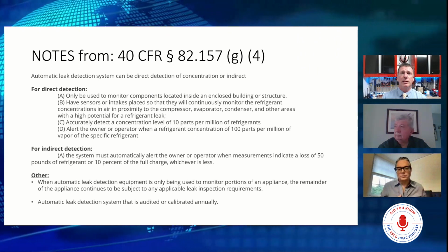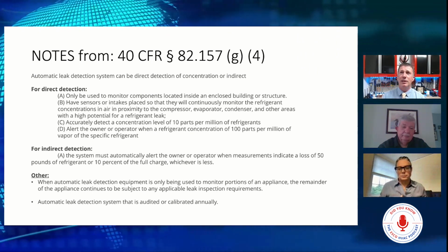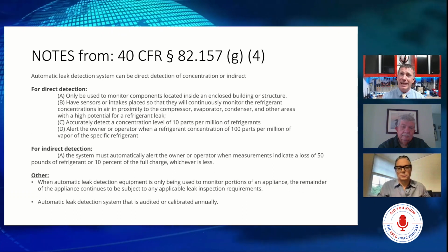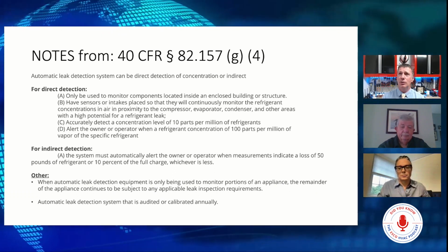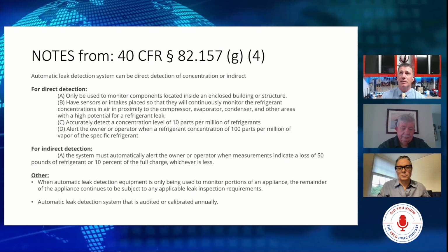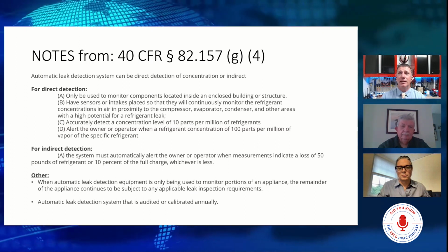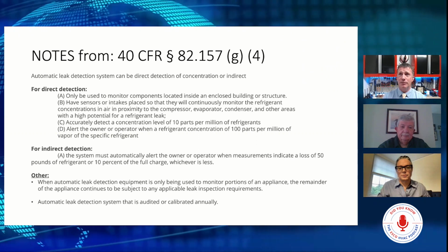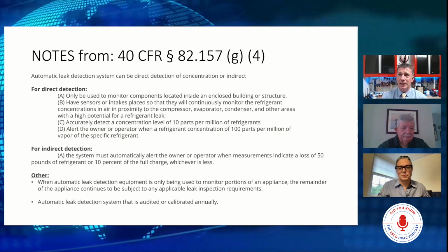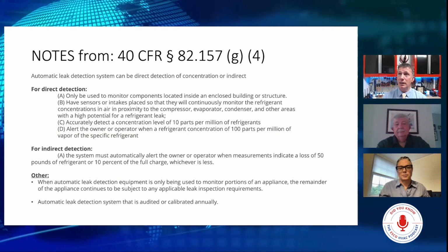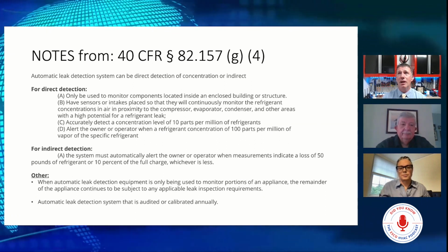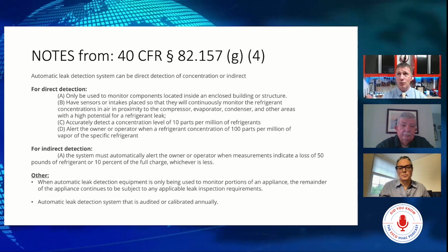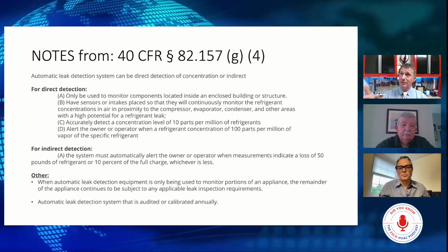One of the problems with total direct leak detection, if you think about a modern grocery store and how far apart the cases are from the actual rack rooms or from the condensing systems or where your monitoring is, can you imagine if we have to have a direct refrigerant leak detection system for all of your remote cases in a grocery store? That's a lot of space that has to be covered with technology. And so that's when we start talking about this new indirect detection, which is really your specialty.